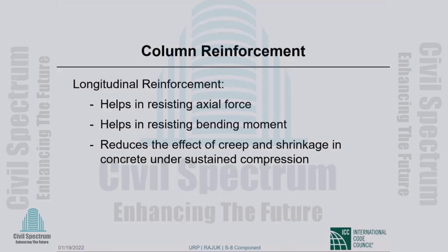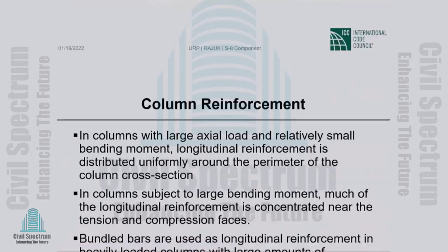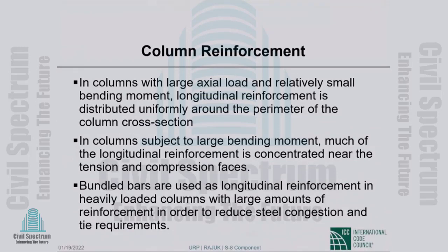Deformation has to be equal. And that requires a load transfer from the concrete to the reinforcement, which does take place. So the reinforcement helps in a couple of ways against the effects of creep and shrinkage. This is in addition to resisting axial force and resisting bending moment.